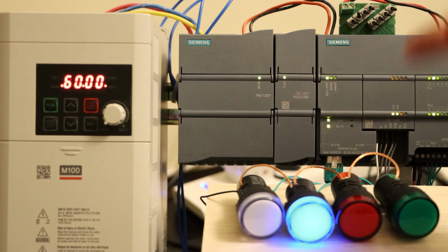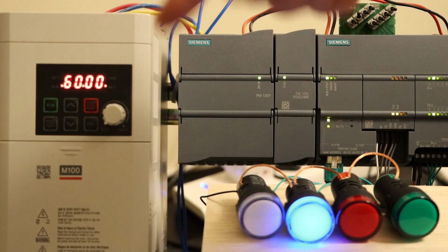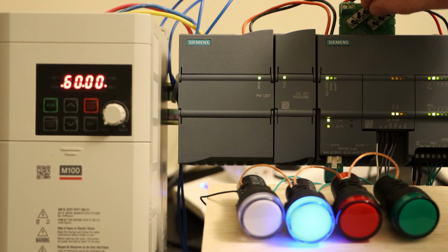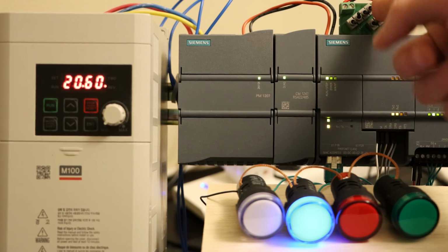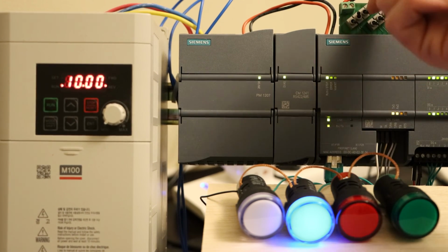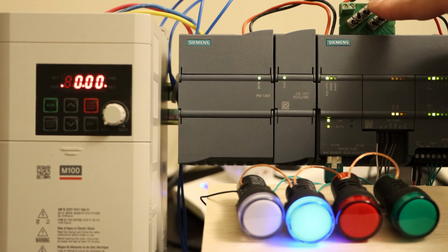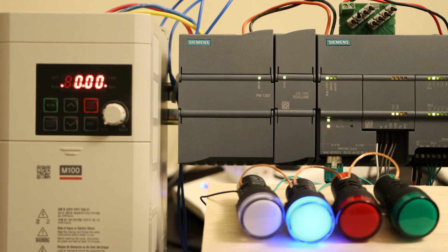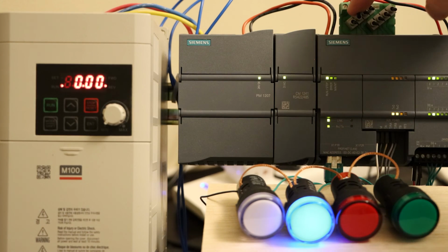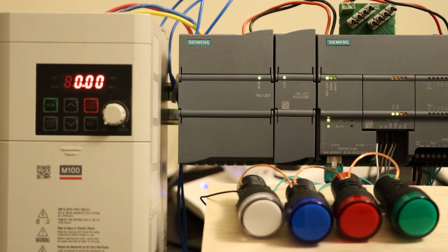Lovely stuff. And even as it's running, if I wanted to change the hertz, so we're at 60 hertz in reverse now, if I just blip switch 4, we actually bring that down by 10 hertz and another 10 hertz. Lovely stuff. And we can actually bring this down to 0 using these switches. So it would be stopped, but we are effectively still in reverse because we're still sending that number 4 into the operations part of memory. So we can stop that by changing switch 2 to off.